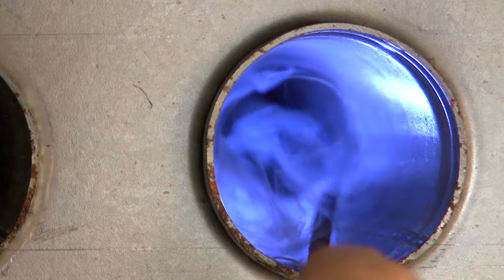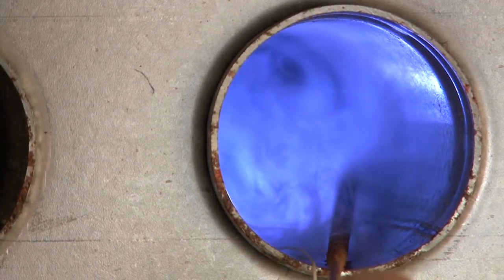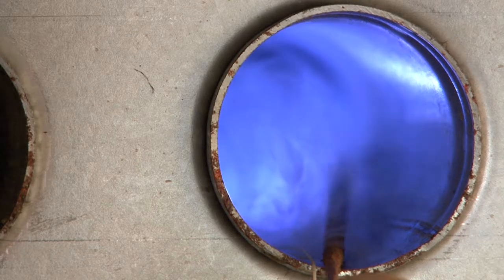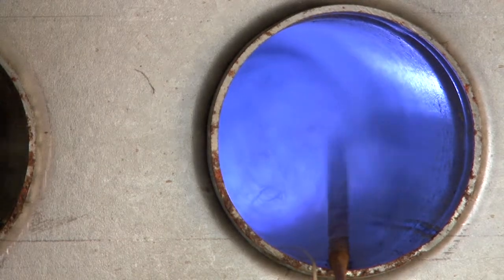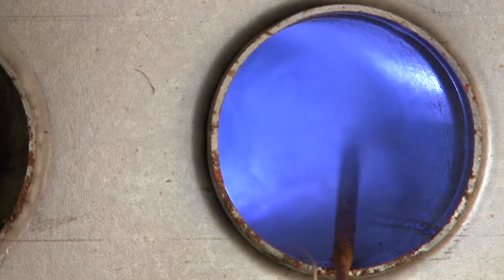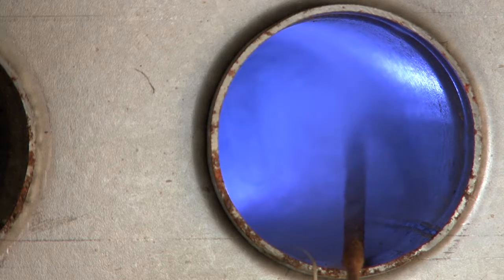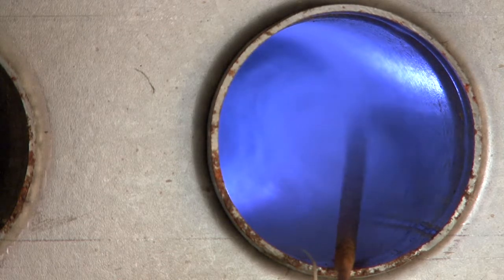And as you can see up in there, all you should be seeing is just the smoke kind of lingering up in there. It's got nowhere to go. You don't have the inducer running, so you're not sucking air through the heat exchanger, so the smoke shouldn't be moving, unless you've got some kind of impingement in that heat exchanger.